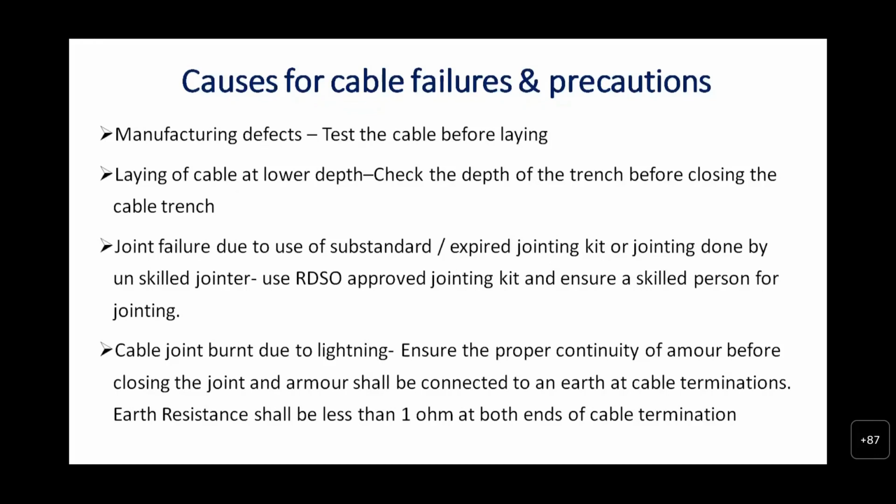Cable joint burnt due to lightning. Ensure proper continuity of armor before closing the joint, and the armor shall be connected to earth at cable termination. Earth resistance shall be less than 1 ohm at both ends of the cable termination.